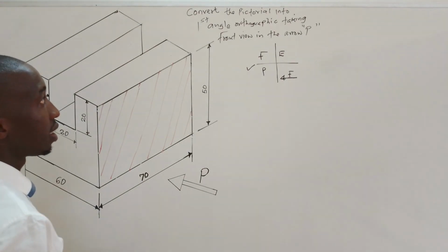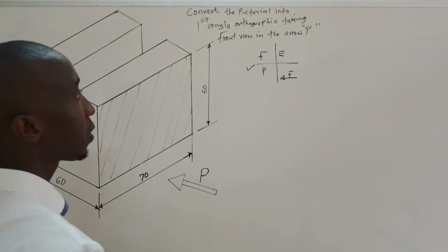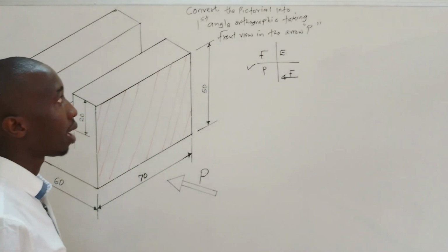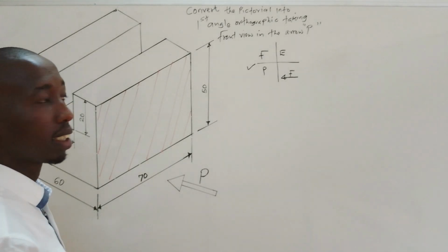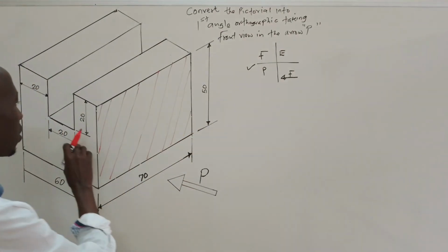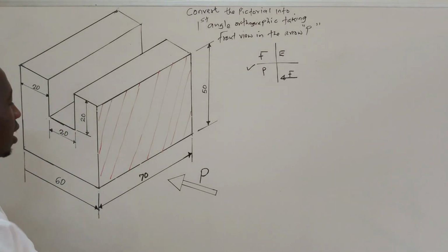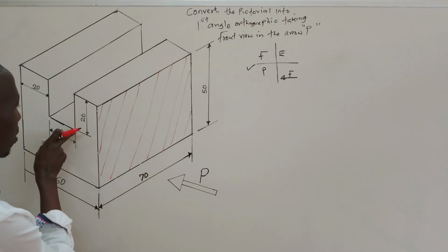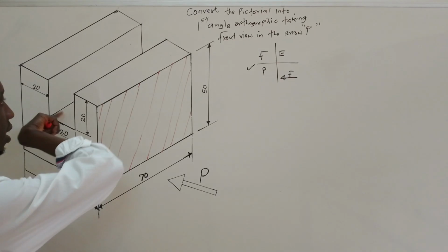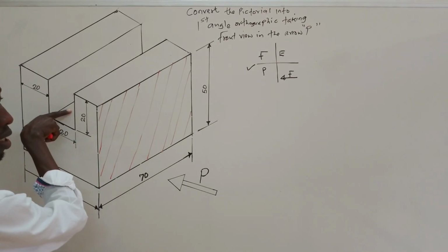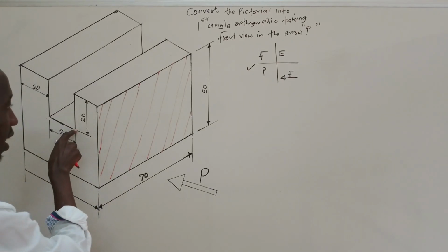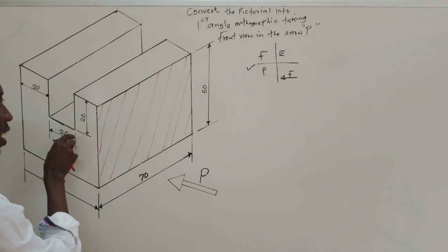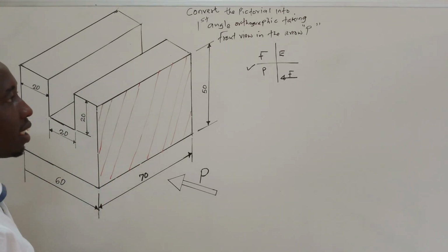If you can refer to my second video on this channel about the broken lines and the center lines, I've clearly shown what is hidden inside here. So we have this corner as a line which runs inside this hole and it is hidden. We'll have to represent these hidden lines on this surface when we are drawing the front elevation.